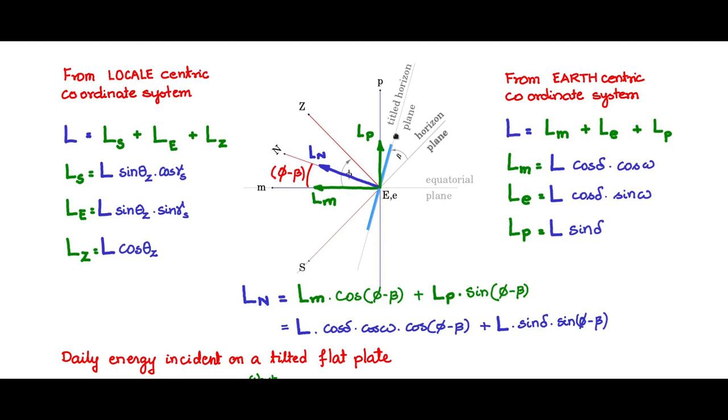When it rises above the tilted plane, you will see that the omega_SR would actually be smaller, measured from the meridional axis, than what it would have been for the horizon plane. Therefore, what we do is take the minimum of the hour angles as computed with respect to these two planes.